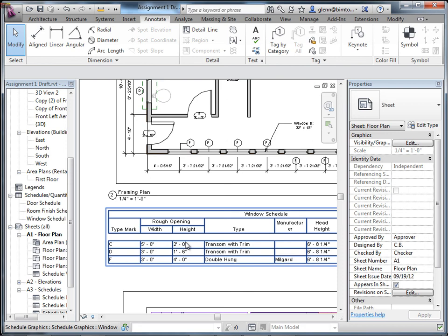Okay, so you want to start thinking about these sheets in terms of how you're presenting the information. For the person who's getting a sheet, what information do they need? The truth is, if you start breaking information across 5 different sheets, chances are when someone grabs that sheet and goes out to the job site, they're not going to get all 5 of them, or they're not going to look any further than what they can see on the first sheet. A lot of times people are not good about going back through your entire book of details to find that detail. You have to be really clear about making it obvious where there's additional information available.